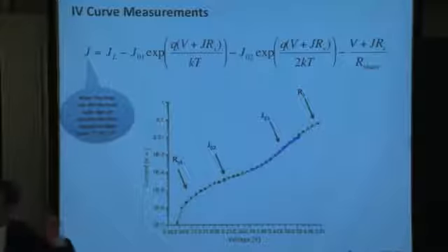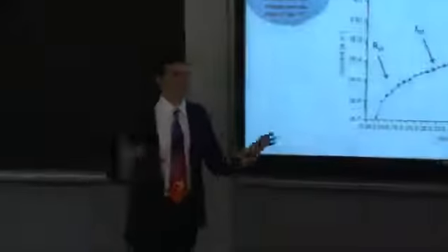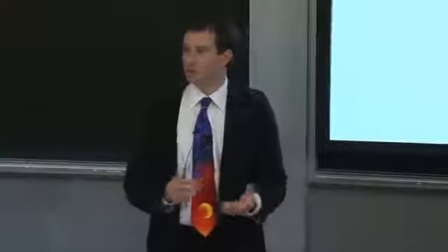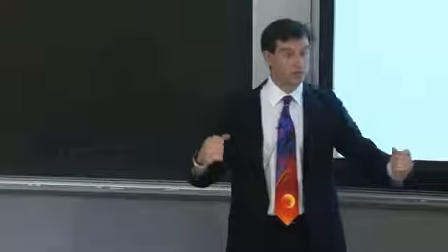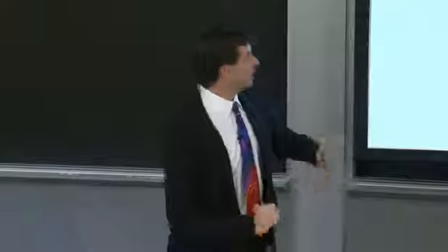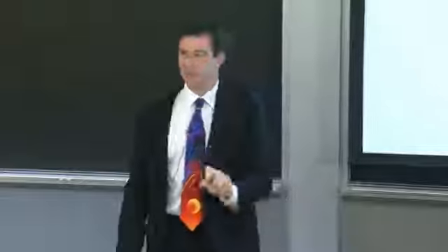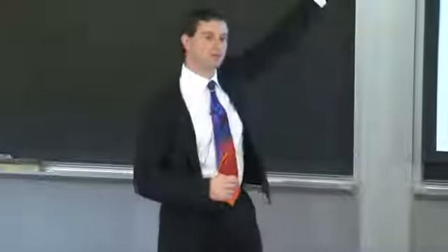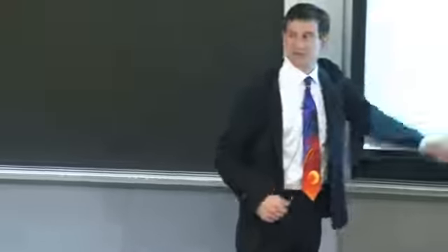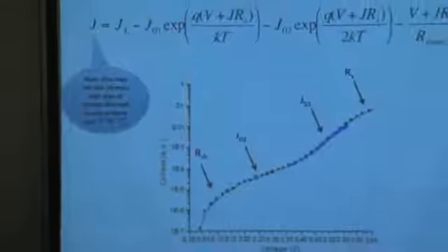Think of the IV characteristics of the solar cell similar to, say, the constitutive relations of a complex viscoelastic material where you have, say, a nice linear elastic component, a dashpot component, right? So you have a very complex expression describing the stress-strain relationship in material. A similar thing goes on here with the solar cell where you're describing the current voltage relationship. If you understand all of the mechanisms driving carrier recombination in your material and charge separation, you can come up with an expression that describes very precisely the IV characteristics. But if you change material systems, you may not necessarily be able to transition the same models over.